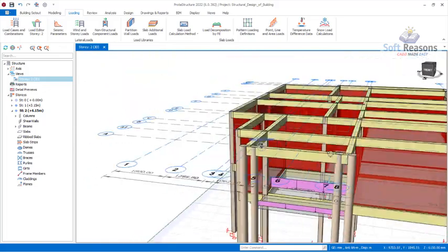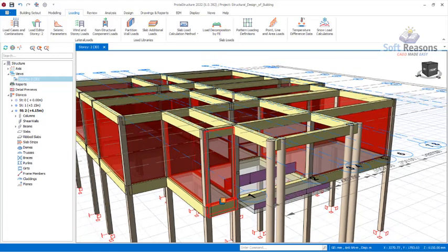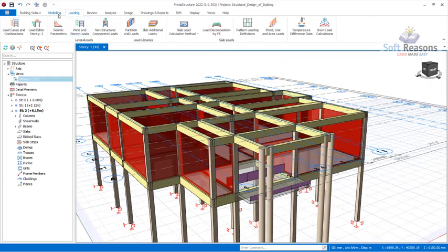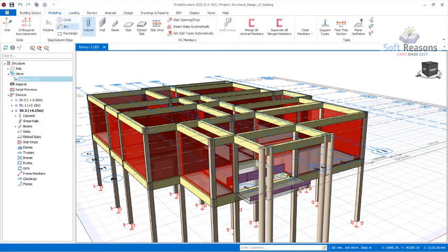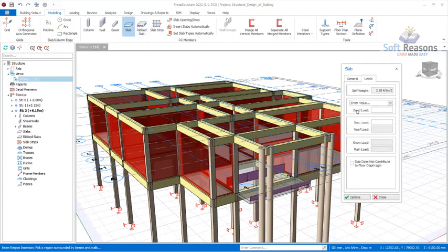To apply that on this roof beam, to design the roof beam so it can withstand the parapet successfully, you just have to get back to the modeling right there. Before then, save this project. Then click on the reinforced concrete slab. So we have some settings here. We are considering partition finishing for this case to be 1. Then we wouldn't have any imposed load, because people don't normally walk around there.